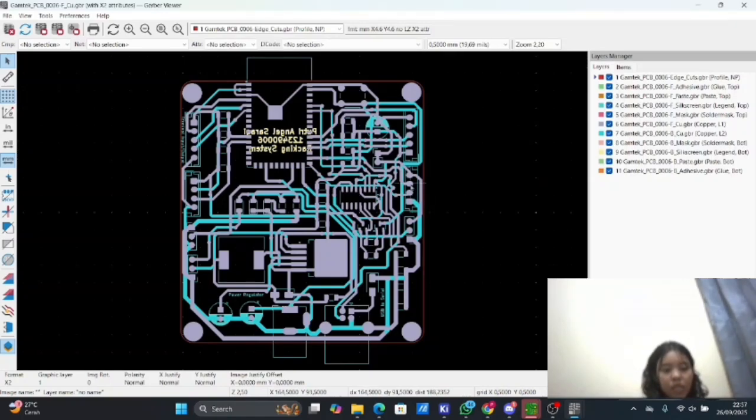Finally, the Gerber job file is sometimes generated automatically by PCB software to describe how the layers should be interpreted, and all the Gerber and drill files are usually compressed into a single zip file to be sent to the PCB manufacturer.